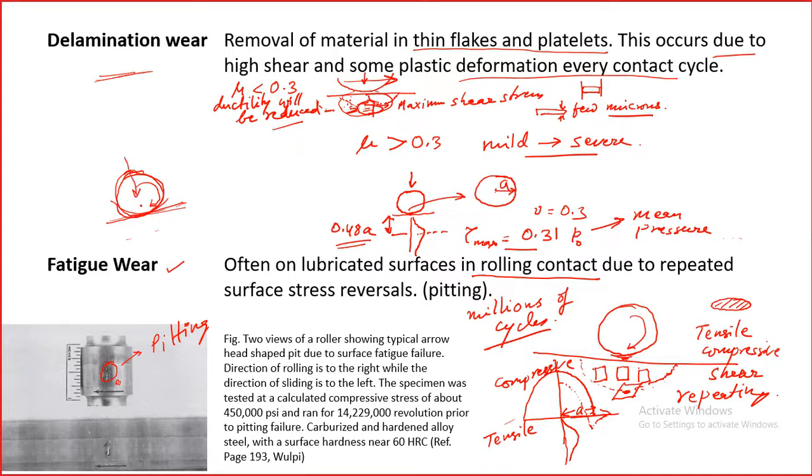So stress will be very high, and therefore there will be maximum shear stress here. At the maximum shear stress, because of plastic deformation, a crack will also initiate. So a crack will initiate here. So even hard material will be subjected to this crack initiation.